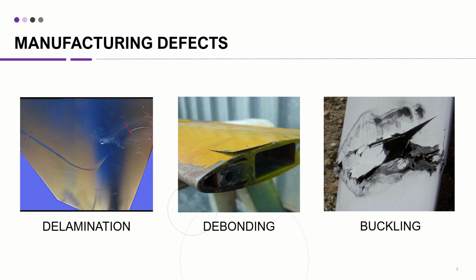Delamination can occur when air is trapped between the fiber bundles of a blade due to poor resin infusion. This causes cracking between the layers. Debonding is a deterioration of the adhesive agents that are used at the interface between various structural elements. When the adhesive has deteriorated enough, then the layers will separate. Finally, buckling occurs with overloading of the blade, where the shape changes and cracks. This may happen at lower loads than expected due to the compounding effects of other defects.